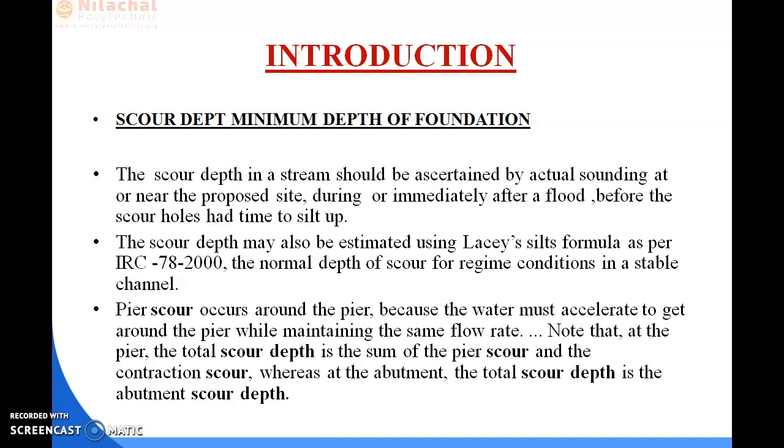And basically the scour depth may also be estimated using Lacey's silt formula as per IRC 78-2000, and the normal depth of scour for regime condition in a stable channel, and for the natural stream in alluvial bed is given as ds equal to 1.34 (q square by small f) to the power 1 by 3.